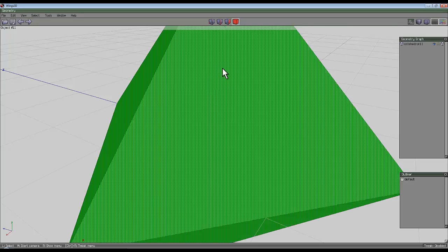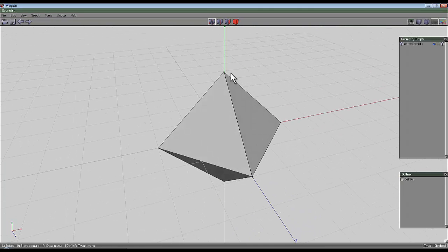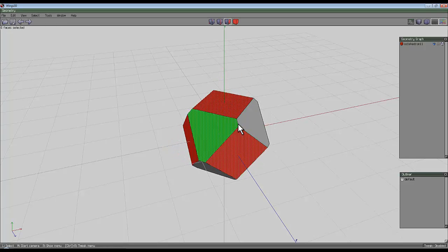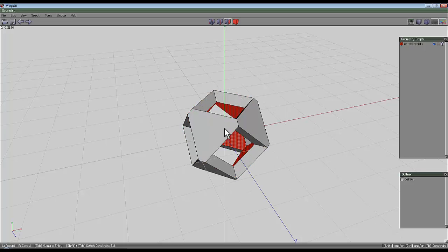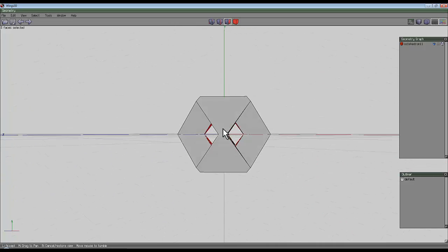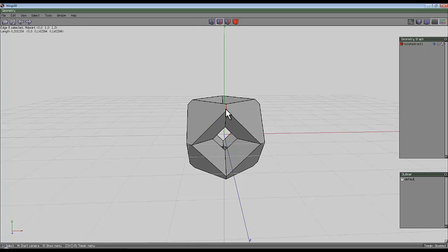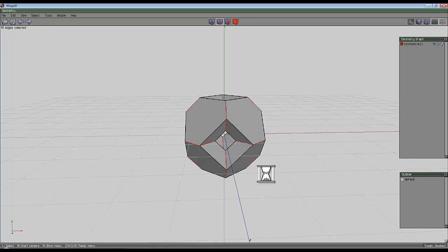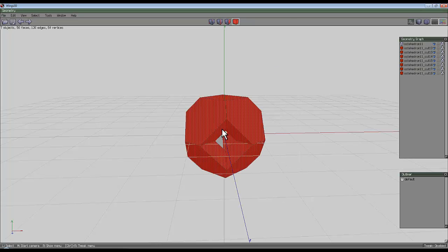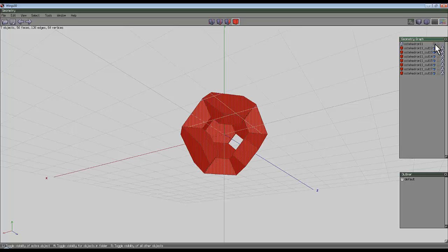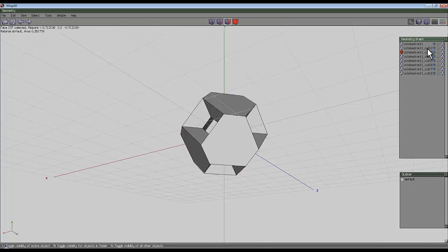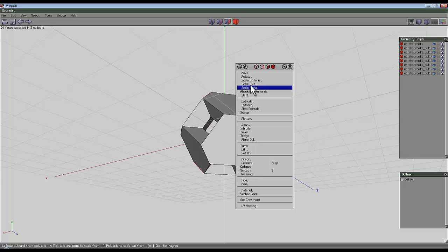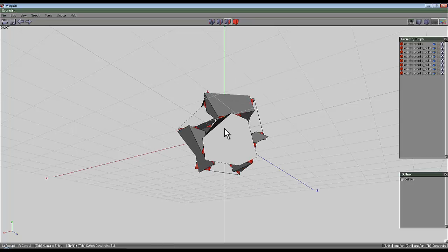So octahedron, right, which is closely related to the cube, and I select these outer points and bevel them down, and then remember at this point to intrude and not forget that bit, so intrude that a bit. Okay, and then press space, get the edge, select one of these outer edge bits, identical, loop, circularize, stop there, right click, loop cut, find the deselected one, hide that, press space, select one of these squares, bring that back in, identical, right click, rotate normal.